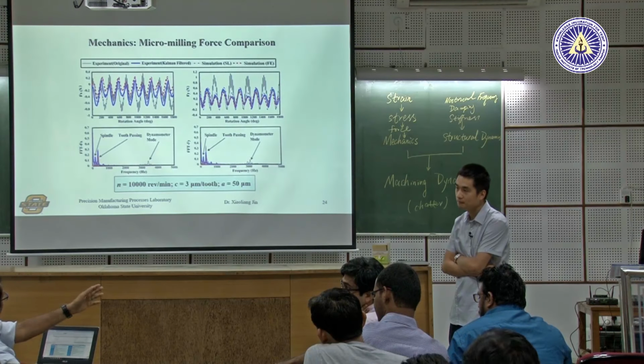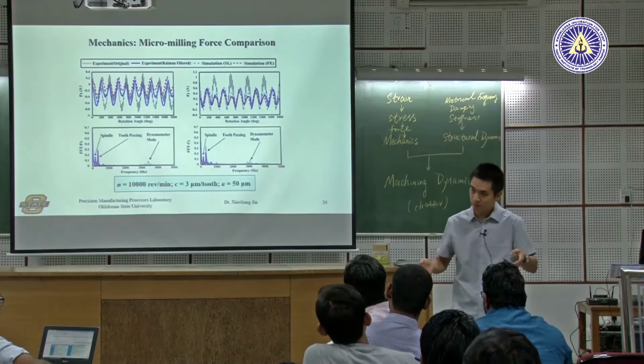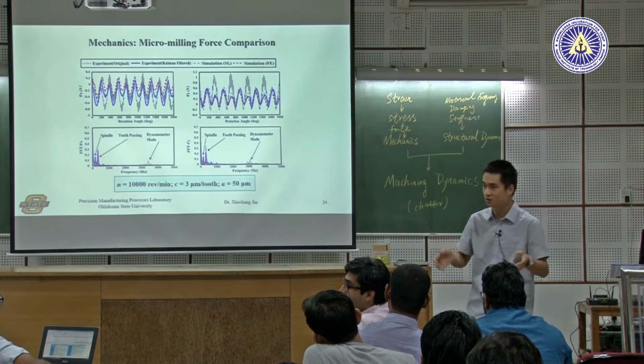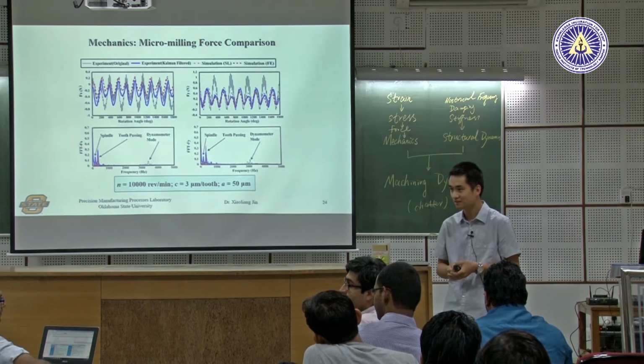And this machine has to stay on a vibration isolated pad. And it has to be in a room with at least some temperature control, not precise, but maybe plus minus 1 degree Celsius, which if you have the ventilation, it can be.